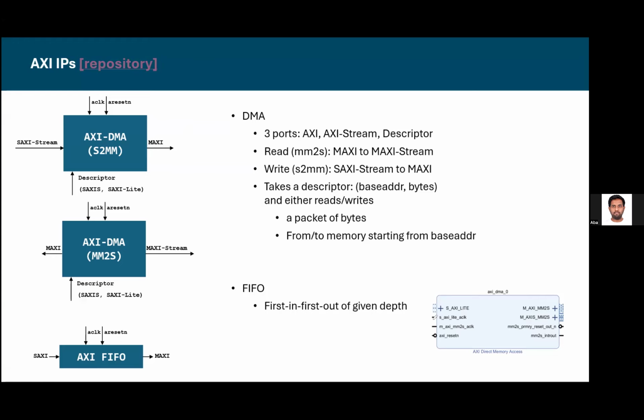But writing a full AXI slave is pretty challenging, right? You can find some good posts from ZipCPU and others on how to write a good slave, and that is very difficult because AXI has all these weird conditions, and you have to satisfy all of them. The data might come first, the address might come first, and there are all these different addressing modes. So you have to handle all of them. It's actually a pretty good exercise if you can write a good slave.